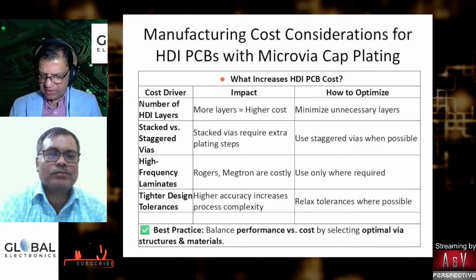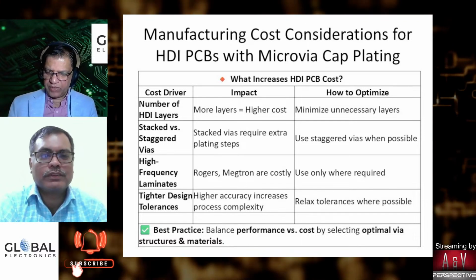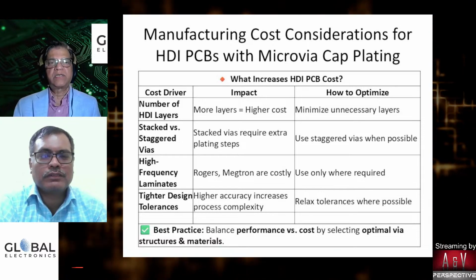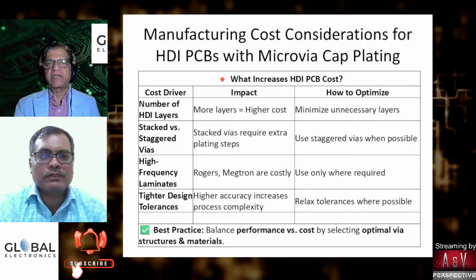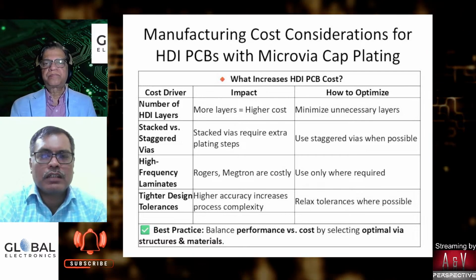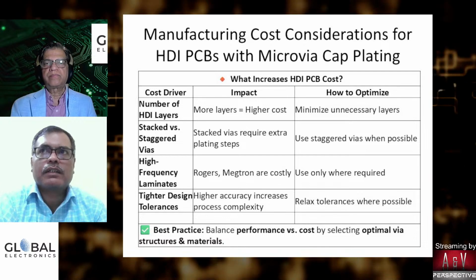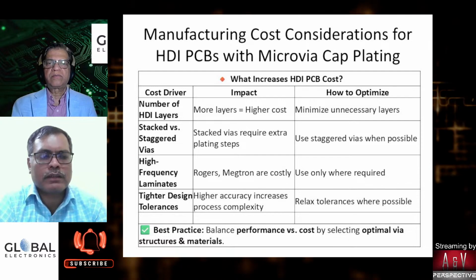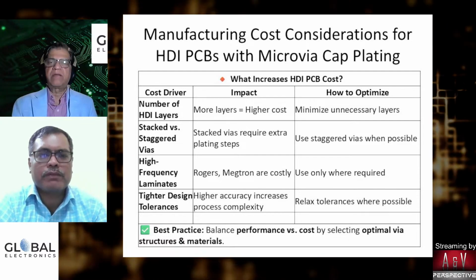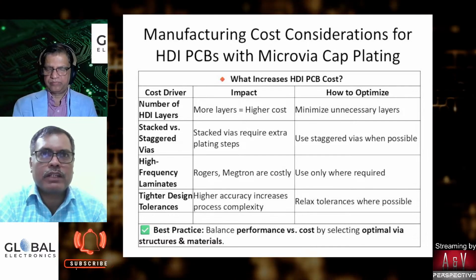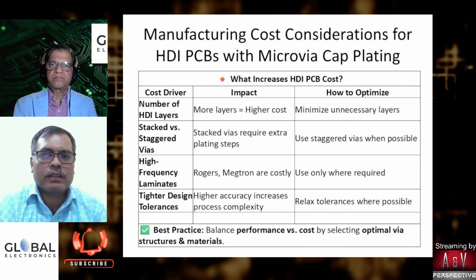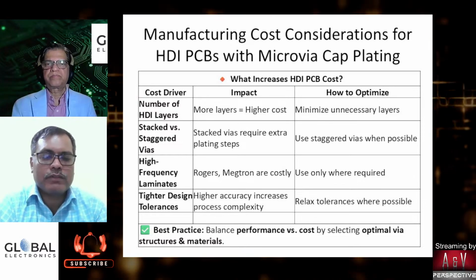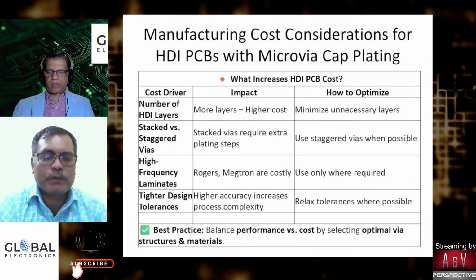One question I have received: what kind of approvals are needed for a defense application for the PCB? There are many approvals required. The main one is MIL approval, MIL standards, MIL-PRF-31032. That standard is there, so any PCB manufacturer will have to undergo that approval.